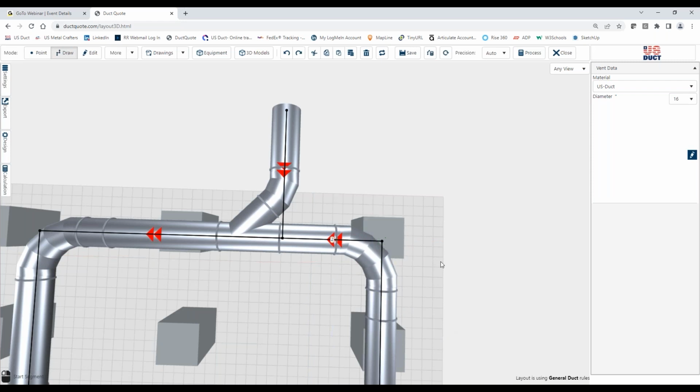The lower the degrees, say a 30 degree, there'd be even less pressure loss or fan pressure required for a 30-degree elbow than a 90 because we're turning it hard. And what really causes that fan pressure is when the air starts to tumble, or what we call turbulence, okay?